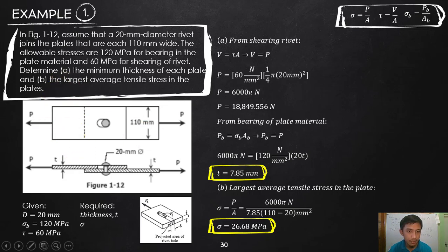Look at this, there are two possibilities. It's either within this full width of the plate, so that will rupture at this entire width, or, using our previous knowledge that the lesser the area, the bigger the stress. In order for us to have a lesser stress, you should increase the area. So the bigger the area, the lesser the stress. If I cut here, that is a full width of the plate. Compared if I cut here, look at this.